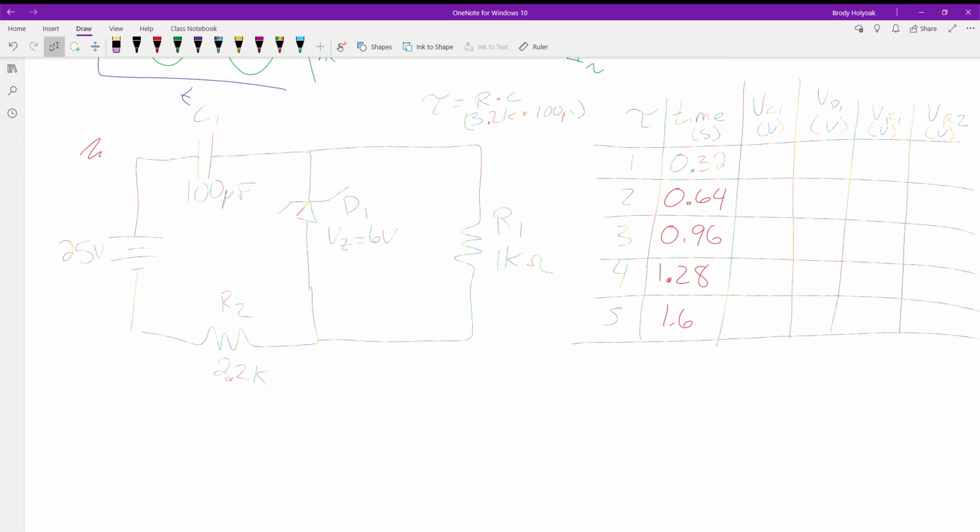How do we know it should be in reverse bias? It's a Zener, because we're given a Zener voltage. A Zener diode is supposed to operate in reverse bias. Does that mean it'll always drop 6 volts? If it has 6 volts, yes. That's the biggest thing. If there's 6 volts available in the circuit, this will drop it, and nothing more.